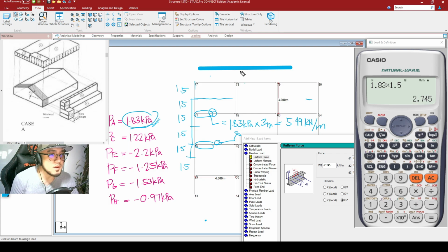So this is to be 3.6 meters. And the original node-to-node distance is to be 4 meters. And for your 2 alpha, which is 1.8, it should be measured from node up until node. So node to node, this is now to be equal to 1.8 meters.